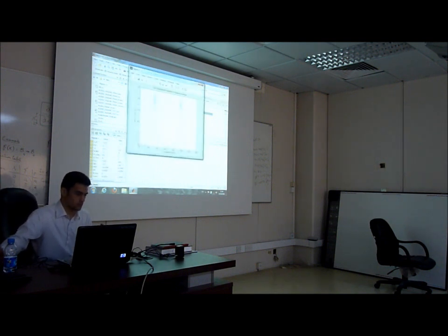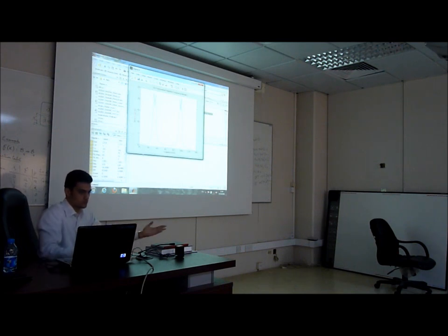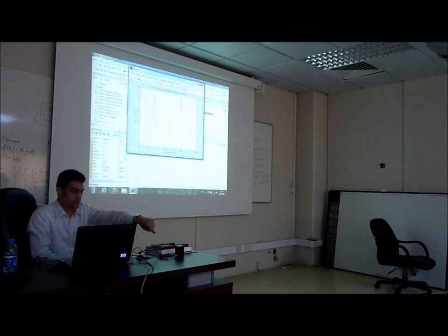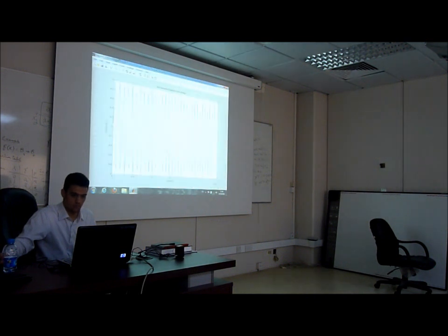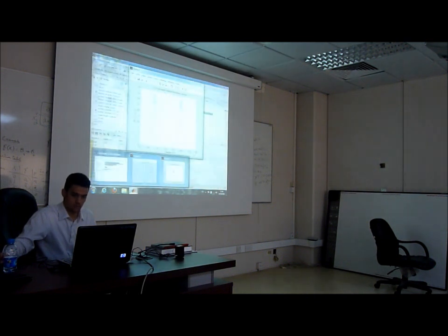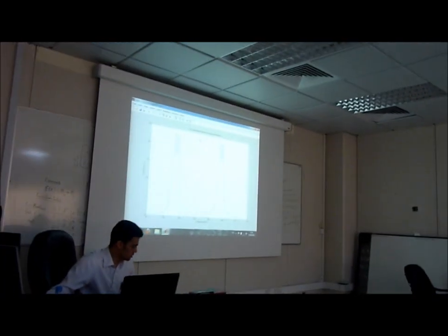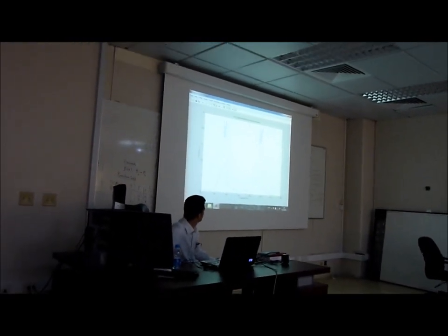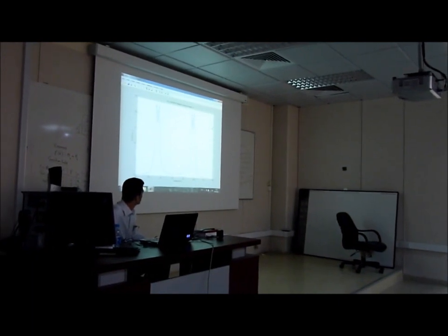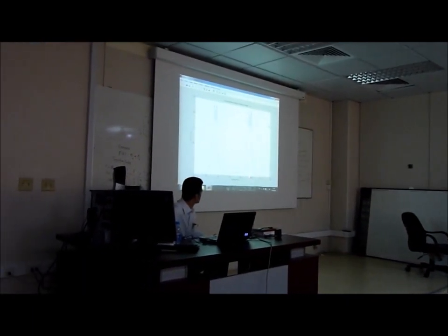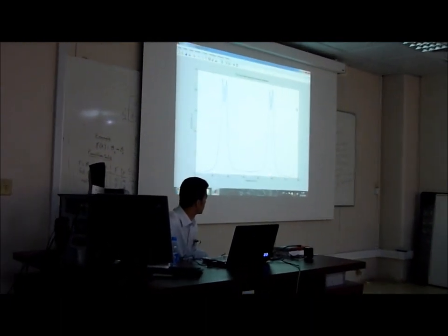The sound we've heard is the transmitted signal going out from the speaker, reflected by the target, and then received by the microphone. This is the transmitted signal in time domain, as you see for the chirp. And this is the Fourier transform of the signal, which is the transmitted signal in frequency domain. You can see it has two big pulses at the frequency that we've used for transmission.